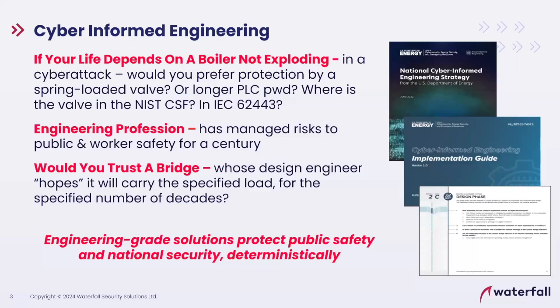It's unhackable. It does not matter what kind of cyber attack is launched. There's no CPU in the mechanical valve. With a valve in place, the boiler cannot overpressurize. The gurus that I asked the question of say, Andrew, you're being deceptive here. You're asking me the wrong question. If my life depended on it, I would want a mechanical valve. I'd want 3 or 4 of them because these things do wear out. Okay, they corrode. I would want a longer password on the PLC, and I'd want a boatload, an absolute boatload of cybersecurity beside it, because this is my life on the line. And they're right. They're absolutely right.